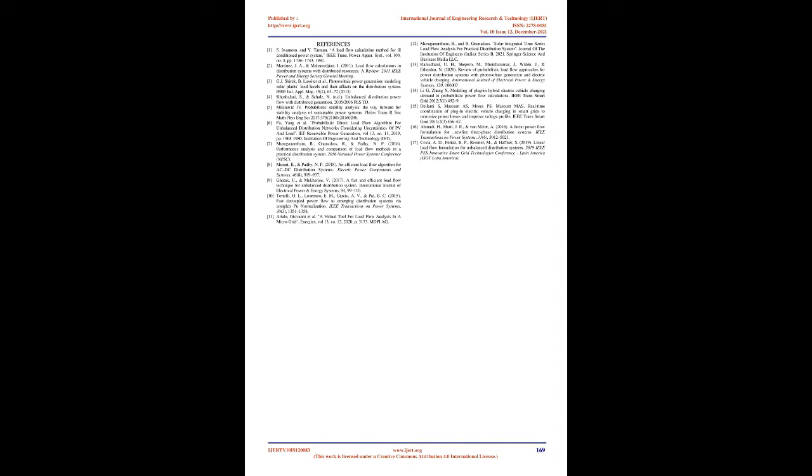B. Electric vehicle, EV. The dramatic increase of electric vehicle, EV, charging in the distribution system leads to high uncertainty of the DS grid. This uncertainty on the load side is due to new revolutionary EV consumers increasing day by day. The charge of a vehicle is not negligible. The full charge of one vehicle can consume somewhere between 20 kilowatts and 70 kilowatts according to recent data research. 13. The main issue is not only the massive charge consumption of each vehicle, but also different unknown parameters, such as the time and duration of charging, the battery efficiency and capacity, and the number of charged vehicles. Because of that, high voltage drop and a rise in power losses may occur.